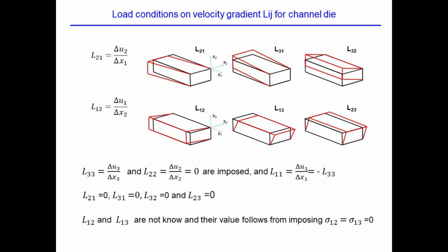Now, of course, this assumes that you have no friction at all, and that the material, when you compress it, is able to shear. Now, if you have friction, the code VPSC allows you to put a value there. You can put 100 MPa, but it's a value that you can set. But to do it right, one should link that value to some friction model to set that component, but in principle it doesn't have to be 0.